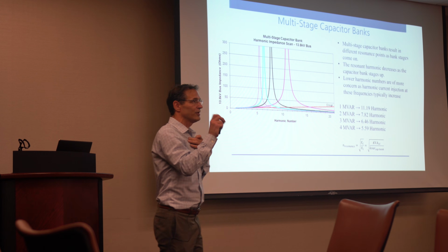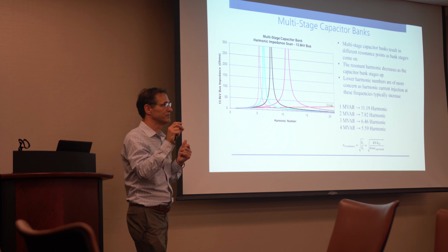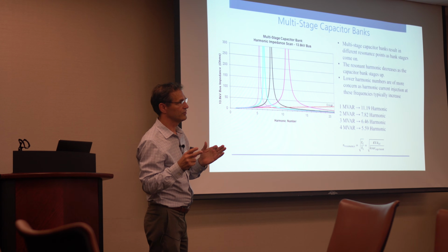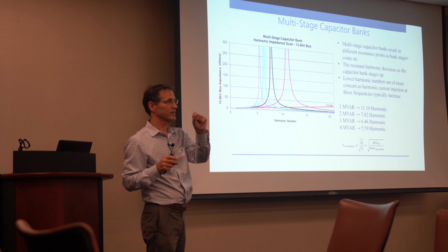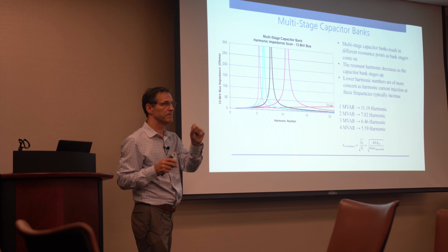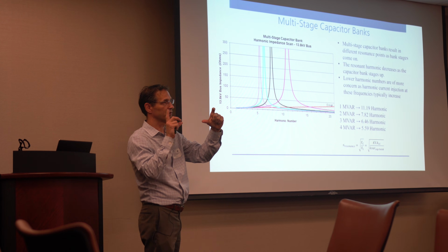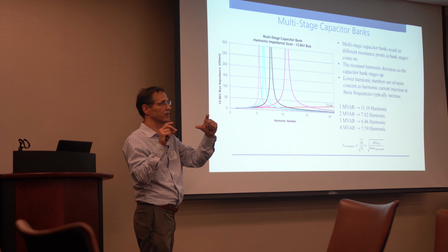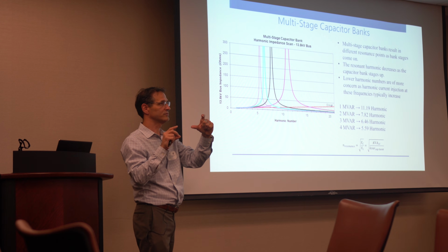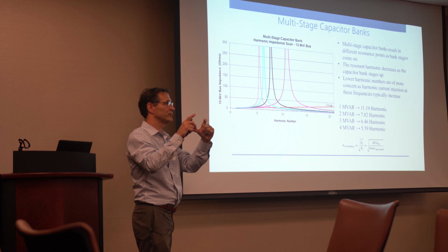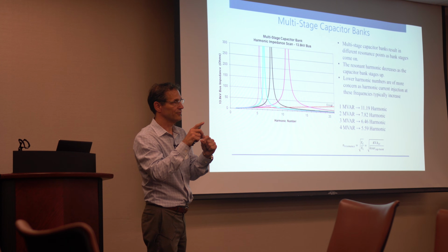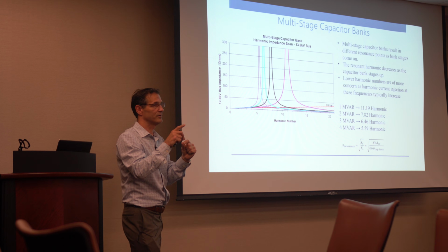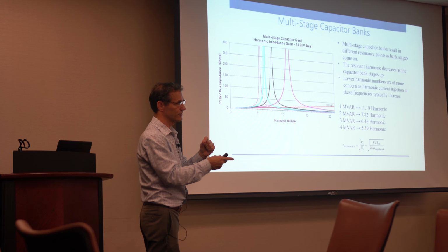In my opinion, I have to click on every condition, and EasyPower is good in this regard because it instantly puts the VTHD on the bus, and I can identify the problem right away. I can also impedance scan and click the one line, open the tie, close the tie, open the main, close the main, go min, max, and average source impedance, right, on the source, and I can look at the impedance at every time, and then I can quickly evaluate which conditions I'm worried about, document that one case, and say all the others are good.